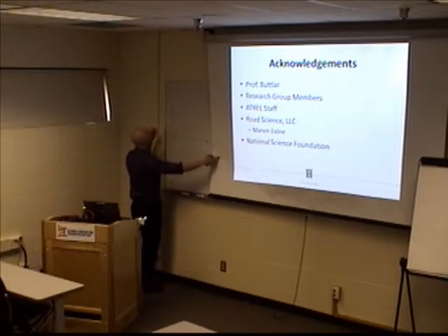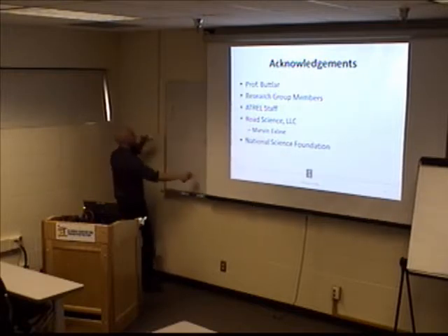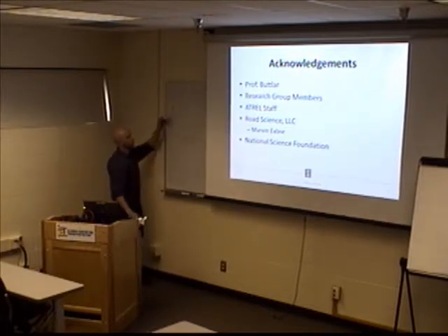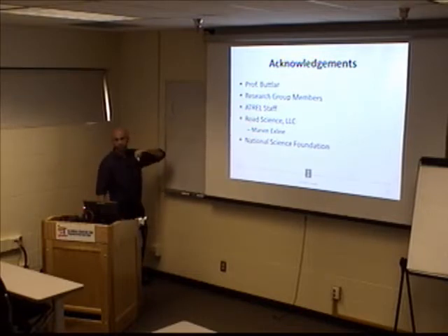In general, with cohesive zone models, you have a traction, I guess I'll just put T, as a function of separation. When you look at the local parameters, specifically, and I believe it's an extrinsic model, right, that doesn't have an initial compliance to it.